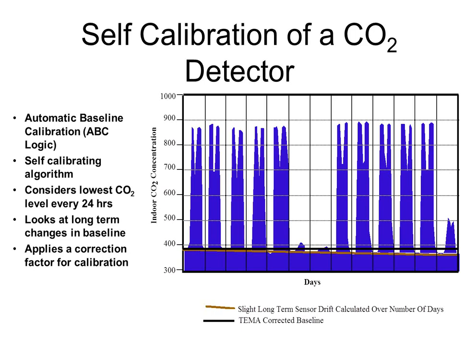That's enough time for most buildings for the outdoor air to seep in all the cracks and crevices and the CO2 levels from inside and outside to neutralize with each other. And the outside air levels are always the same number. Now, sure, they change over the decades, if you will, right? But on a day-to-day basis, it's always the same number outside of parts per million of CO2. So basically, it self-calibrates itself to the outside air levels every single night. That's basically how this works.